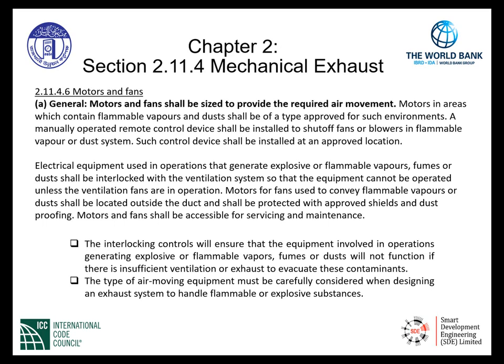So the key requirements here that we have to make note of is the interlocking controls will ensure that the equipment involved in operations generating the explosive or flammable vapors or even fumes or dust will not function if there is insufficient ventilation or exhaust to evacuate these contaminants.